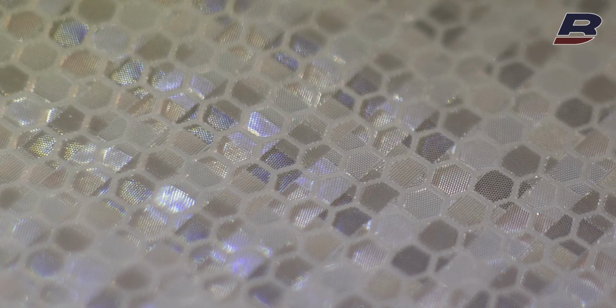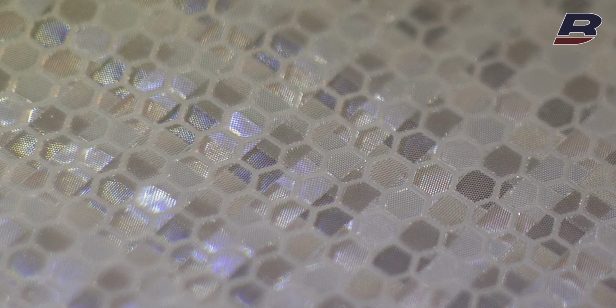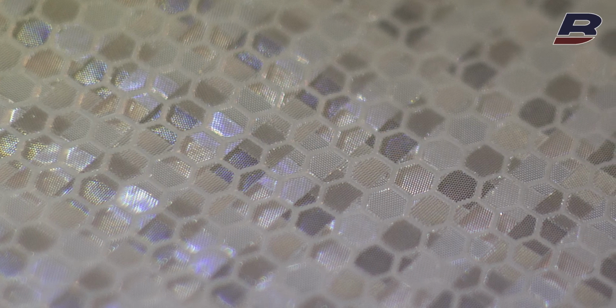Second option is to do tiling. Tiling is creating alternating areas of prisms with different orientations. These areas may look like stripes or squares of different sizes and positions, and it's not a trivial task. Those manufacturers who perform tiling on their product usually have fewer or no limitations for traffic sign manufacturing processes.